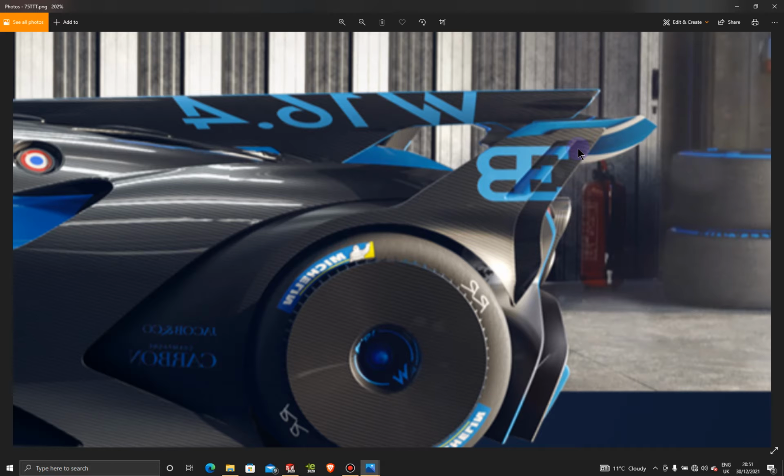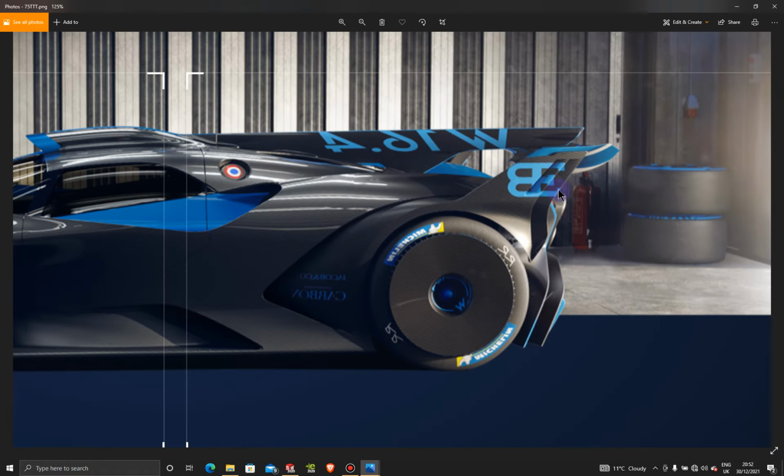Okay, so the way we're going to do that is we're going to cut out this section. We're going to keep a 3D sketch straight on this end, and then we're going to make a surface, and we're going to do a boundary surface onto that inner surface, and the same thing on the second cutting on that surface as well.